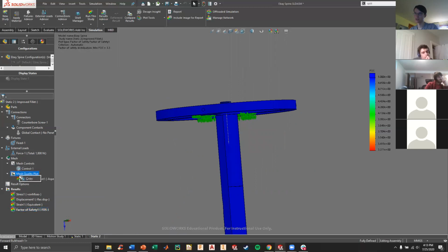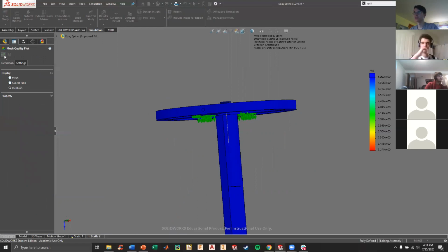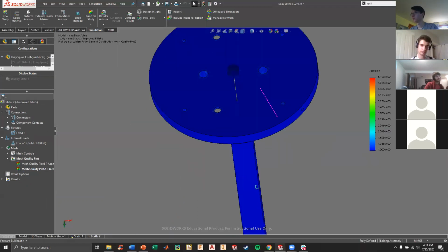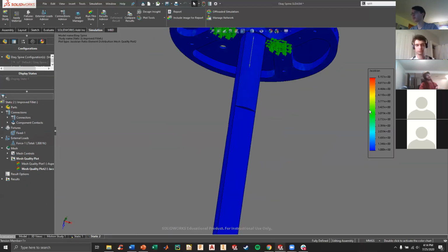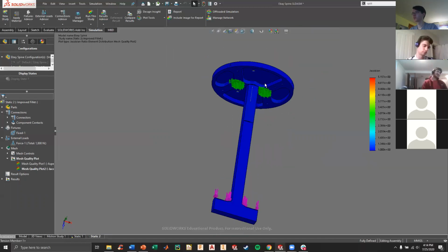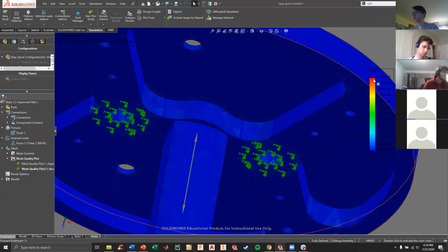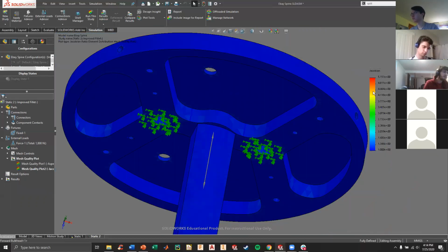The mesh quality is going to depend on a lot of things. We haven't even gotten to the Jacobian quality that you're going to be looking at, which is some other thing I didn't really know. You just want to keep that as low as possible. It's not necessarily a deal breaker, but particularly in the areas of interest, you want it to not be in the red. Not looking at the magnitude necessarily, but just the spread of the results. And there's a whole lot more you can get into, like composites, obviously one big thing that I've been trying to teach myself.